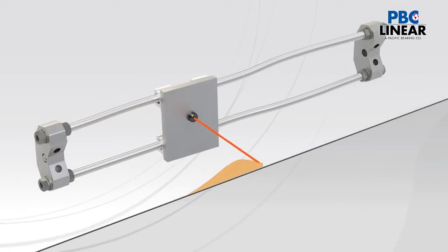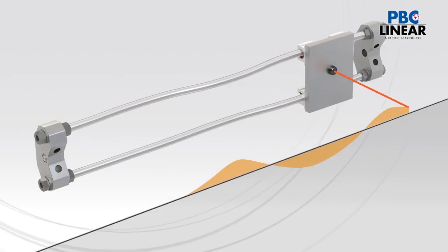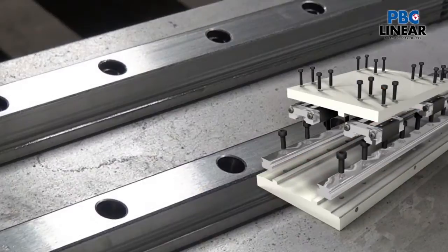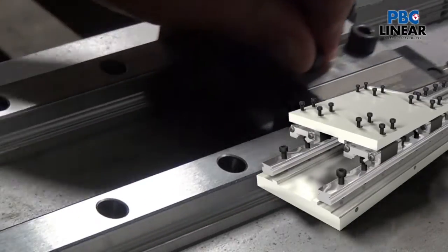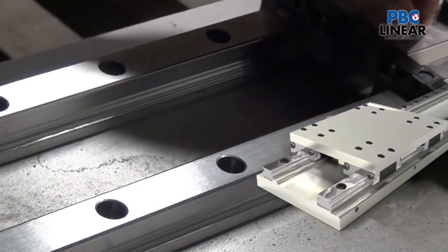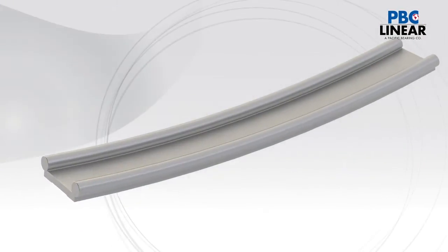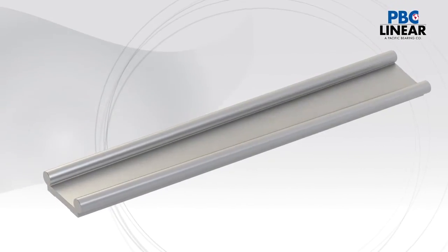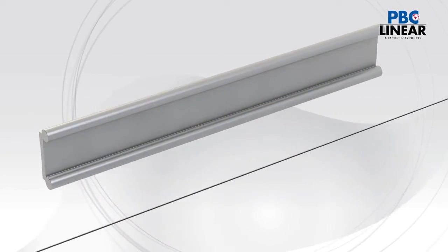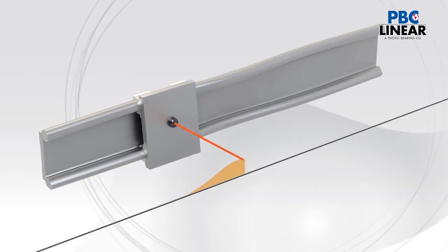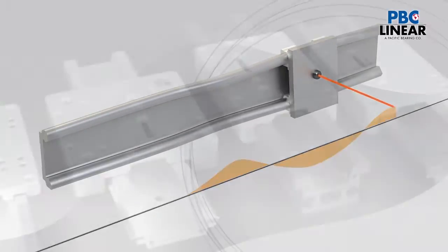Most often, these rails are used in parallel. It can be difficult to mount them without special fixtures or laser alignment tools. They also require being mounted on a highly qualified surface. This can be costly, time-consuming, and still produce inconsistency and misalignment. At the other end of the tolerance scale are aluminum rails that are not qualified or machined. They are made to very loose extrusion tolerances. This lack of precision will have a direct effect on the linear motion system being able to achieve consistent repeatability.